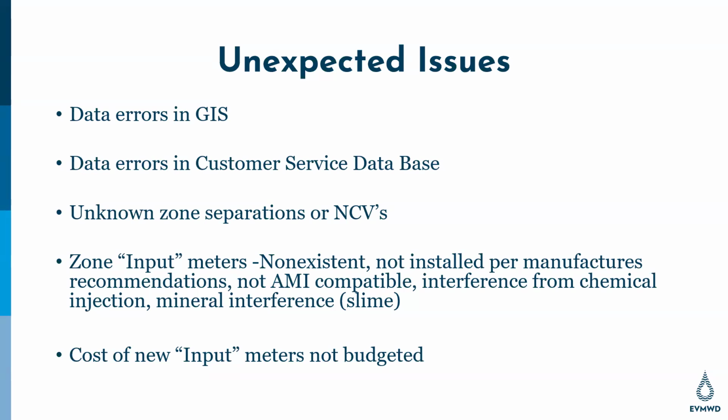We were calibrating our DMA, so to speak. We were making sure all the information was correct. The zone boundaries were a discrete zone, and all the valves were closed. So we went to the meter head and realized there was a cutoff set point that doesn't show flow underneath a certain amount of gallons per minute. That meter was phantomly running at 98 gallons a minute in the background. So that meter had to overcome 98 gallons while it was pumping, and then back to zero, and it threw the whole thing off. It was an oddball thing.